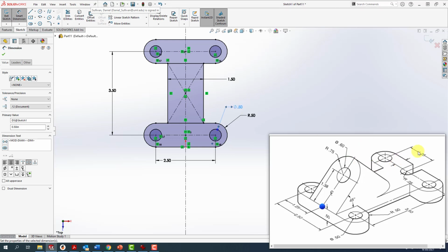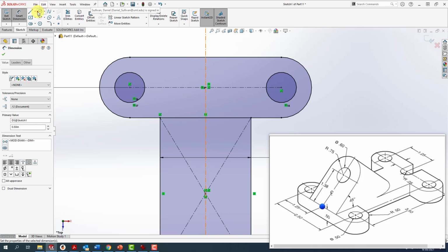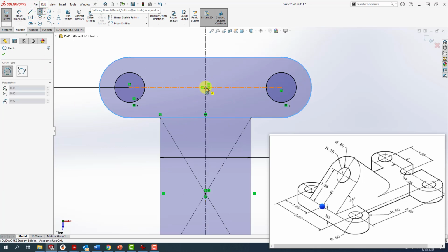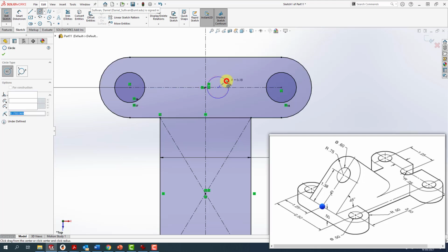We'll note that there's a little U slot cutout. It has a radius of 0.25, which is equal to the diameter of 0.5, and it exists on the same line. So if I come in here and utilize my circle tool, you want to make sure that you get an intersection, so sometimes that might not happen. Sometimes it's more convenient to make sure you get it to be fully constrained, is to click here.